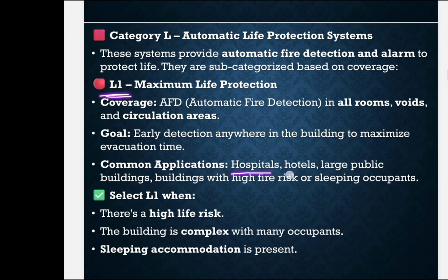In hospitals and hotels, because in both places there are sleeping occupants. Patients get admitted in the hospital. In a hotel, we choose to rest, to sleep. Okay, like some apartment accommodations, there we can use the L1 category of fire alarm detection system.